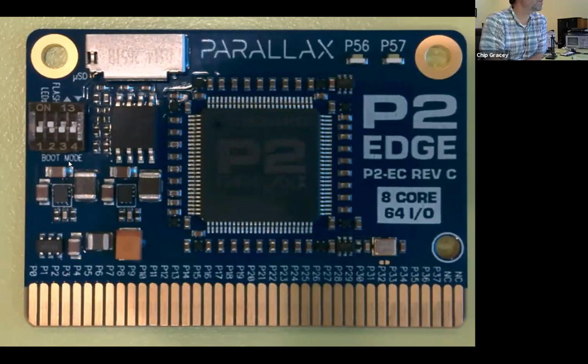So this one here regulates 3.8 volts, and it feeds all of the LDOs that generate 3.3 volts. Because at full load, these little LDOs only need 100 millivolts above, they only need 3.4 volts to deliver 3.3 at max current.